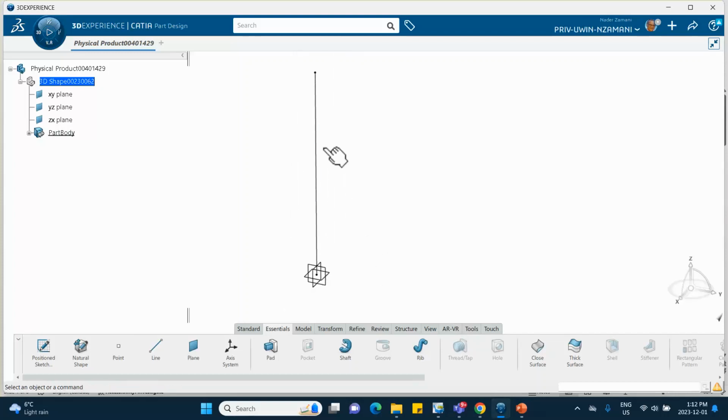Because the cross section of this thing is not a circle or a tube, basically a hollow pipe, I need an orientation point. So I'm going to create an orientation point. The location of it doesn't matter, but you have to be careful, because in this particular problem, you can think about it as an I-beam that is vertically standing up and it's rotated by so many degrees. The orientation doesn't matter.